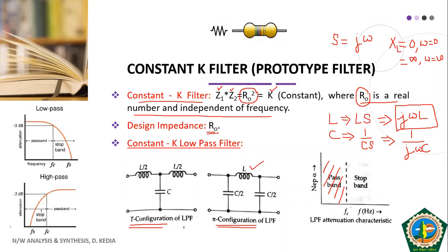What does it mean? When we have 0 XL, it is a short component, and if we have infinite reactance, it behaves like an open circuit. Like if XL is 0, then your inductor becomes a short, simply like a wire. And if your reactance is infinity, then your inductor behaves like an open circuit, meaning nothing can go from here to here.